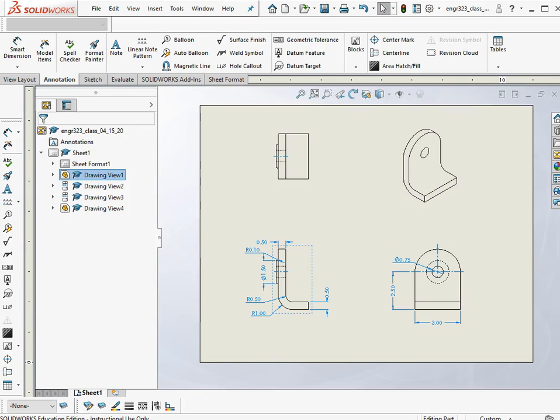So there's various ways you could do this. The method I'm going to decide on is to draw this little J shape here and make that first. So I'm going to make this bottom first, and then I'm going to add the circular bit around the top. I'll put the boss on, then put the hole on, and finally I'll do this fillet. Often the fillets are the last thing to go.